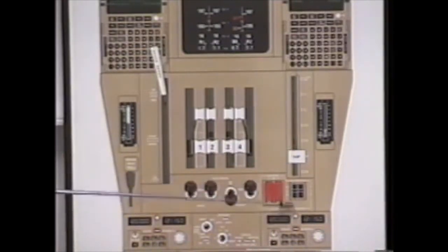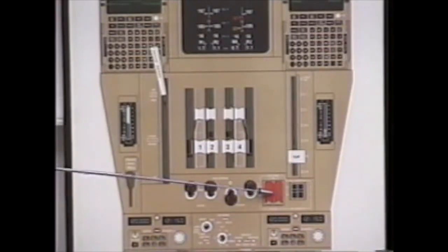Unscheduled stabilizer trim. The immediate action for unscheduled stabilizer trim is to oppose the trim and call for the QRC for that condition. Stab trim cutout switches, one for system 2, one for system 3, is a 3-position switch. If I lift the guard, the switch in the aft position is cut out. The vertical position is auto, the forward position is on.